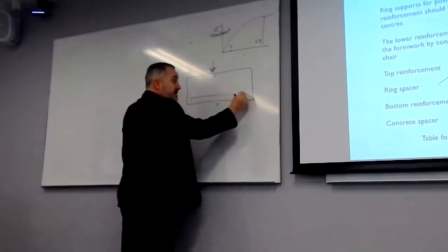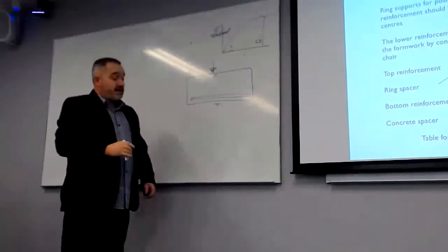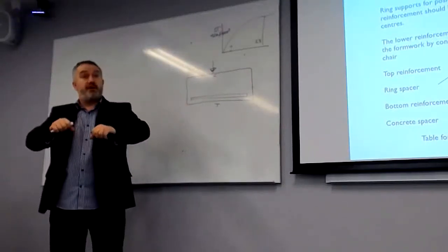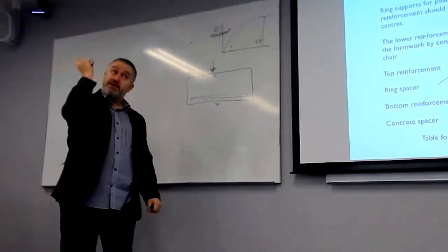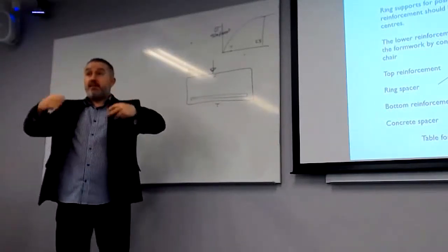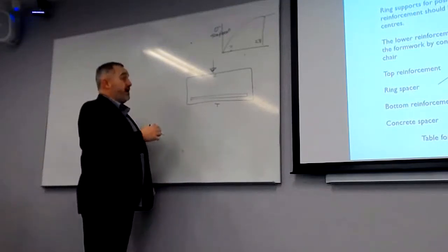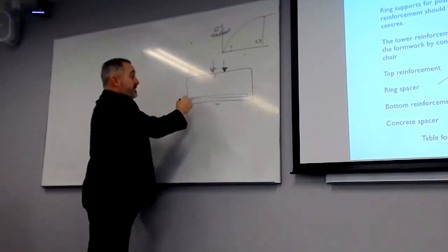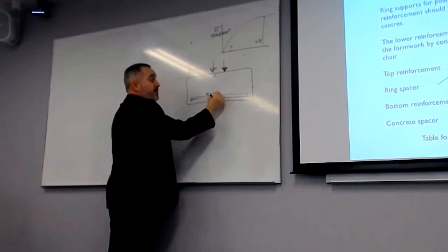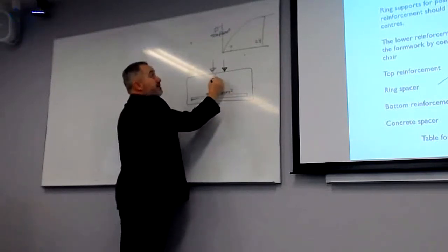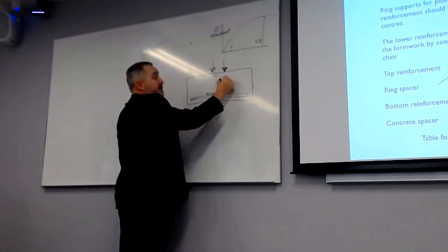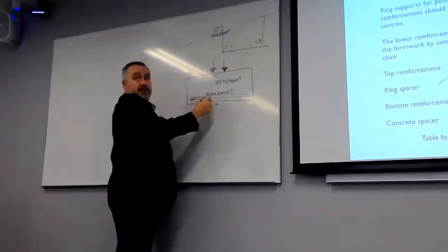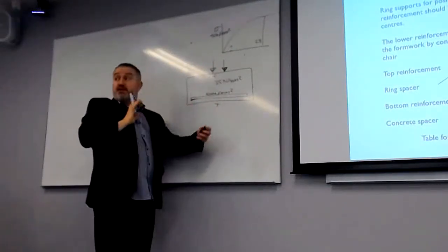So what we do is we put our steel in, and the steel fails first. That's what we want. We want the steel to fail first, so it stretches slowly, which gives us enough time to get out there. We don't want the concrete to snap suddenly, because everybody just dies straight away. But there'll come a point that the load is so massive that the steel, which is 500 newtons per millimetre squared, because the concrete is around 35 to 50 newtons per millimetre squared, is perfectly fine at the bottom, but it's going to fail in compression. It's going to be crushed.